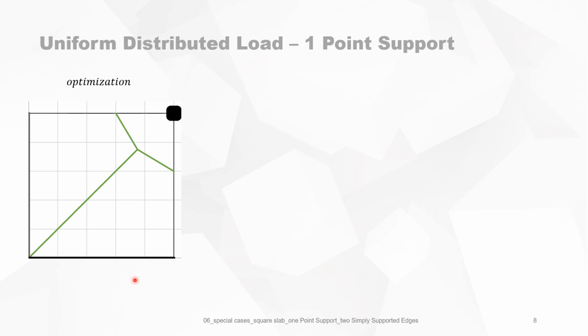Using optimization of the angles, we see that the angle that this makes here, and the angle of that, is 31 degrees. And the maximum bending moment is given by qL squared over 10.67.